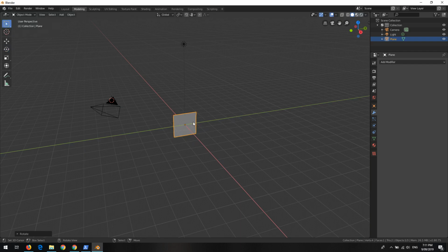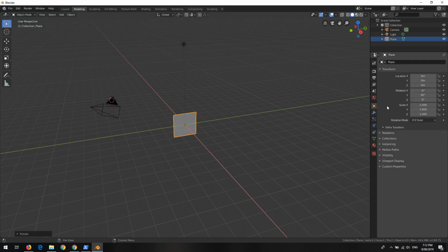Click on the selection. Now we select our plane, and let's go to here, the object properties. Here, object. Now we can see all the properties for the object. The plane is selected, and it's a 90 degree rotation. Let's fix it as it is. I'm exactly clicking. So this is another way, just typing in. So we just rotate it along the Y. Along the Y rotation, we can drag and adjust. Let's set it to 90. So it's now erected fully.